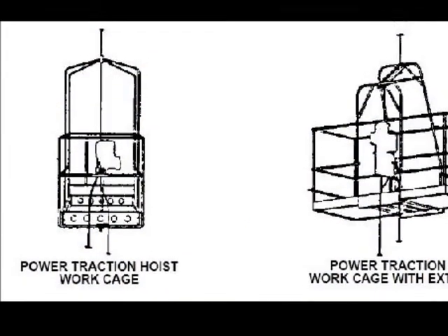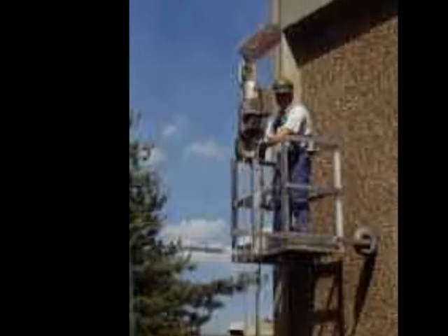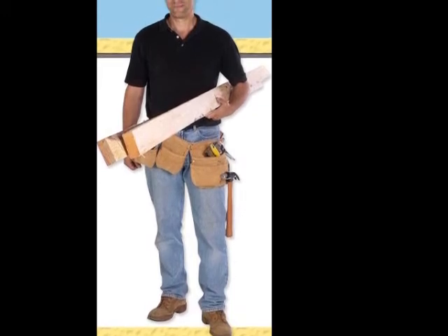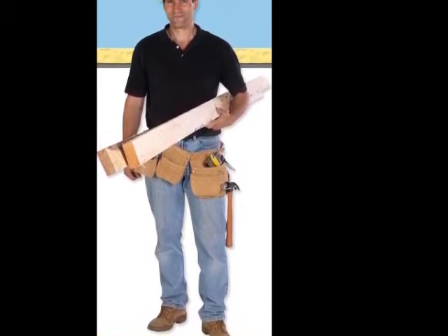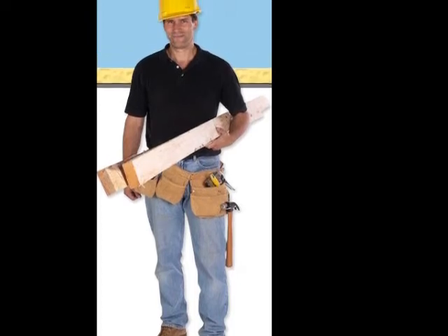Single-point scaffolding is another type of suspended scaffolding. In this scaffolding, the rope between the scaffold and the suspension device must be kept completely vertical. Suspension scaffolding must be evaluated by a competent person daily to ensure ropes aren't defective and make sure the supporting surfaces can support the building.